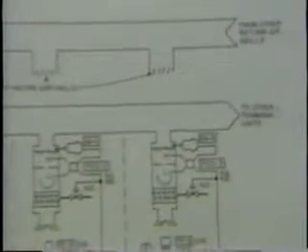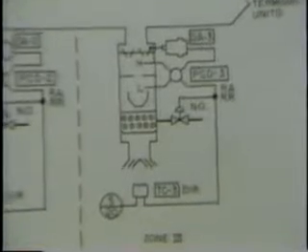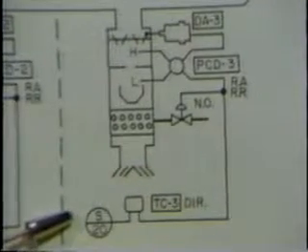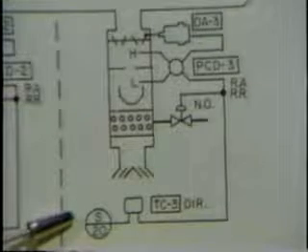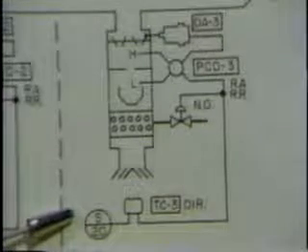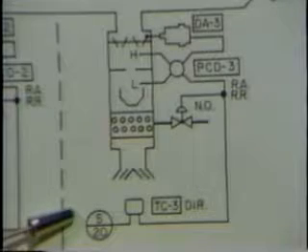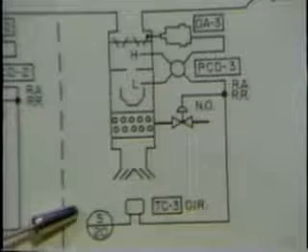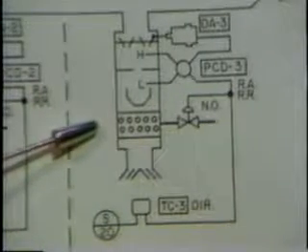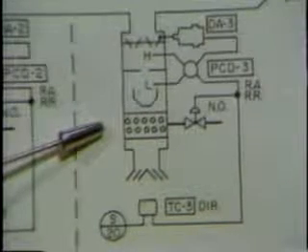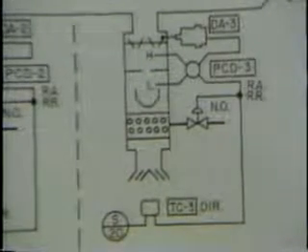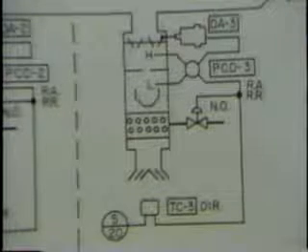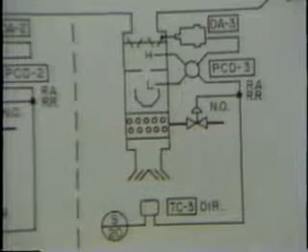System type number 2. Terminal reheat variable air volume systems operate similarly to the preceding system. However, when the heat gain in the space drops or the heat loss from the space increases to a point where the terminal unit's volume has reached its minimum, generally 40% to 55% of design maximum, heating is introduced by the reheat coil. These systems are generally applied to exterior zones. Any introduction of heating to an interior zone which has no heat losses would be considered an energy waste.